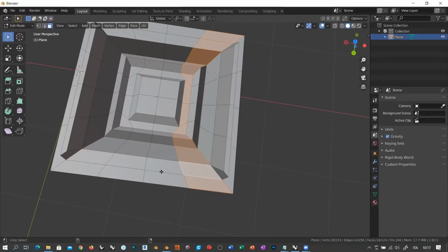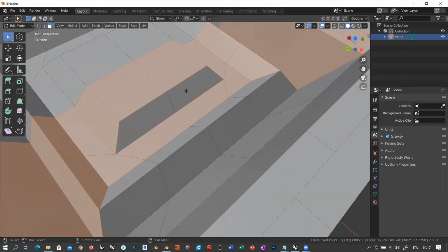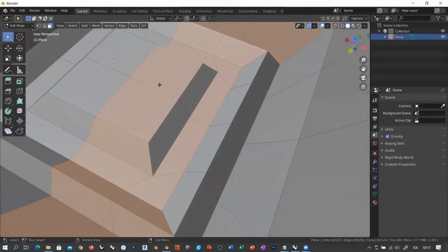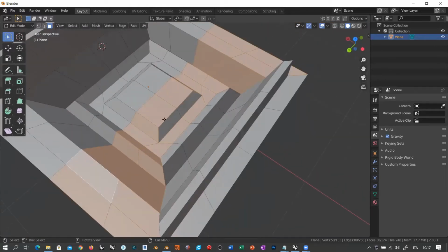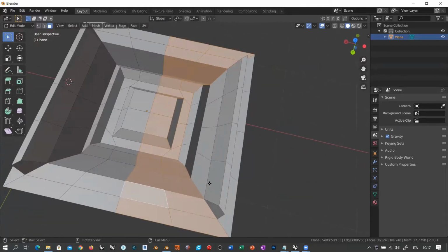And this other one, Shift Alt click, is doing this. What happens to these two polygons? They don't belong to this loop here, and they don't belong to this loop here. So they are basically isolated. They don't belong to any loop that we have selected. Also, if I Alt click on this edge here, you see that I get a cross loop.